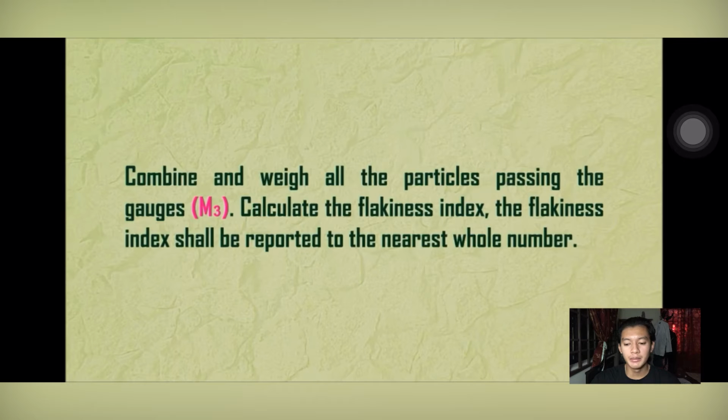Combine and weigh all the particles passing the gauge M3. Calculate the flakiness index, and the flakiness index shall be reported to the nearest whole number.